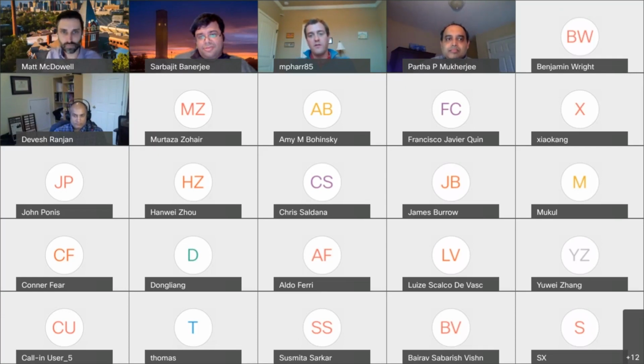Eric Herbert from Michigan Tech did some nice studies with indentation, in which he suggests that you get a transition from low length scales to large length scales, from diffusion type creep to dislocation mediated creep. So there's a lot of ongoing efforts in this area. It's a good question, but there's no definitive answer at this point.